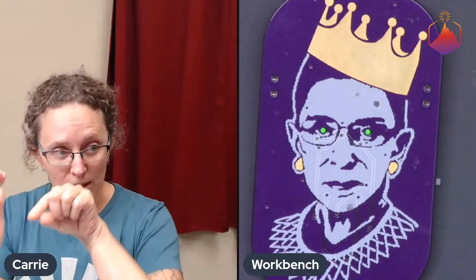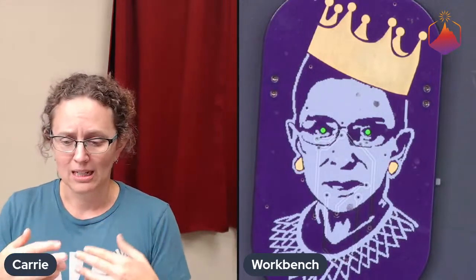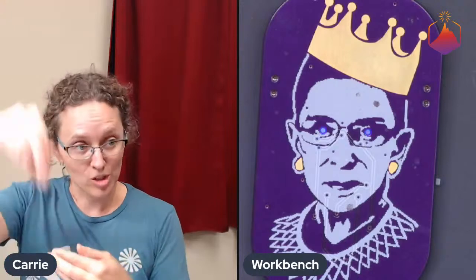And then also, you will see her face looks a little pockmarked, and that's because there are what's called vias, and vias connect two layers of a circuit board together. They're a way of putting a trace that starts on one layer and bringing it to the bottom layer of the circuit board. So this is a 2-layer circuit board. So it has copper on the top and copper on the bottom, and there's fiberglass in between. And so when you need to jump over something but not touch it, you can jump down to the next layer on the circuit board.